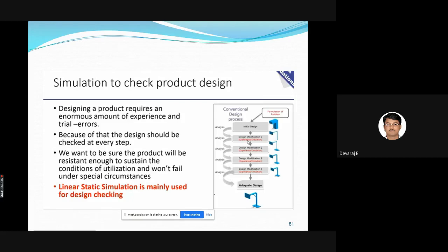I think I told you this in the previous semester in mechanical operation. What is factor of safety? It's like if you're making a material which is supposed to withstand 10 kg of load, you need to make it 2 or 3 times stronger. For a scooter, as an example, sir, it is designed for 2 people, but even if 3 people are sitting, it should work properly. Okay, good. So this is called factor of safety.